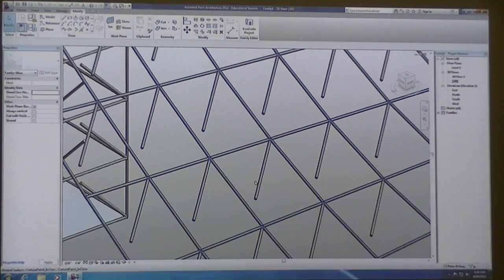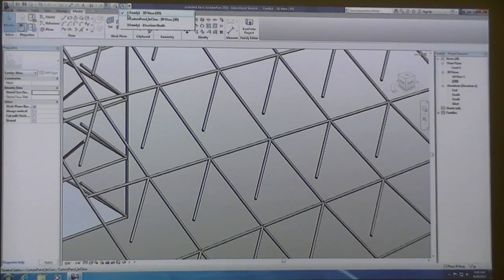So I've got a problem. If you look up on the screen, my actual diagonal is not snapped to the other point. This is where snapping comes in important. And I like to build these curtain panels one step at a time because you want to test to make sure that it's working with each little addition that you do.